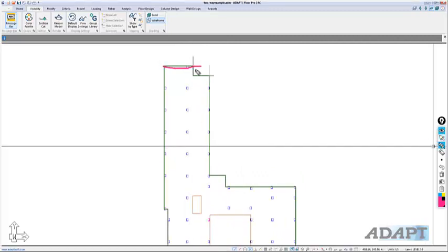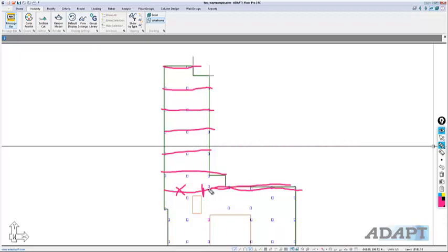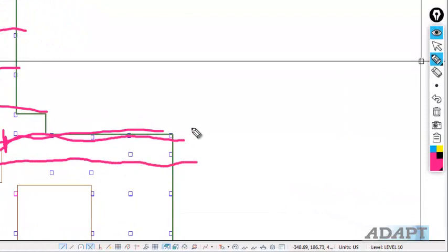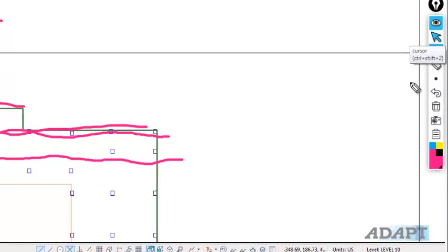So we're creating basically column frame lines like so. I'll actually do one along here. I'll stop it there. This is not going to be there. Or I could bring this across, down, and then out. And then I'll actually put what's called a splitter, which is just a boundary that the program will isolate this area to. Splitters can be used also to control the tributaries that are generated by the program.